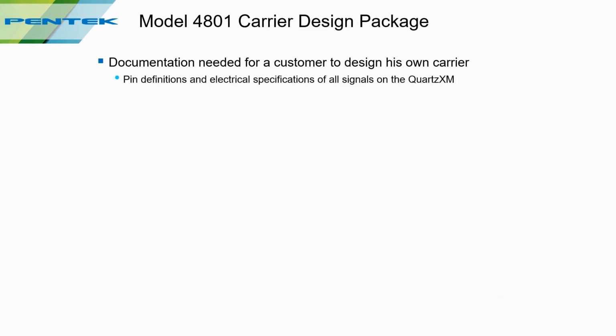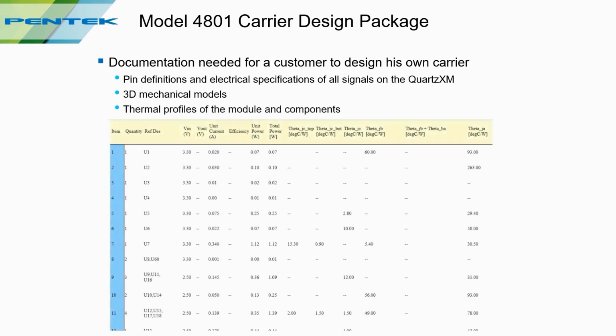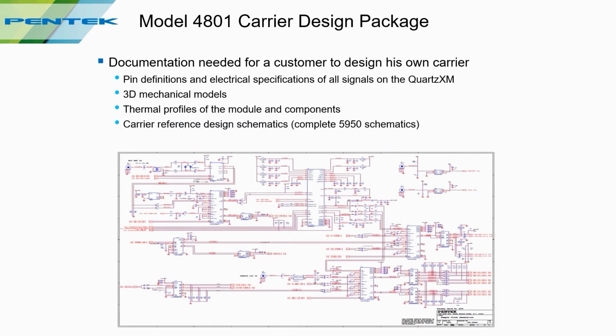And it includes all the pin definitions and electrical specifications of the Quartz XM, a 3D model of the board, as well as 3D models of one of our carriers, thermal profiles of all of the components on the Quartz XM, as well as thermal modeling and measurements we've done. It also includes the design of the 3U VPX carrier as a reference. So we're giving you that entire design, including the schematics.